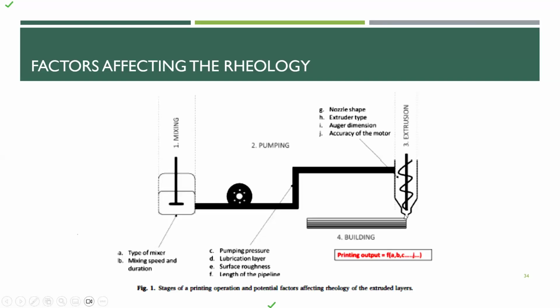So the shape of the nozzle and the speed of the extrusion are also important, and we have to vary the speed based on the requirement. Because we are working with concrete, and you all know that concrete will harden with time, at the start of extrusion the concrete may not be that hardened, and you have to have a specific extrusion speed, maybe like 500 or 600 rpm.